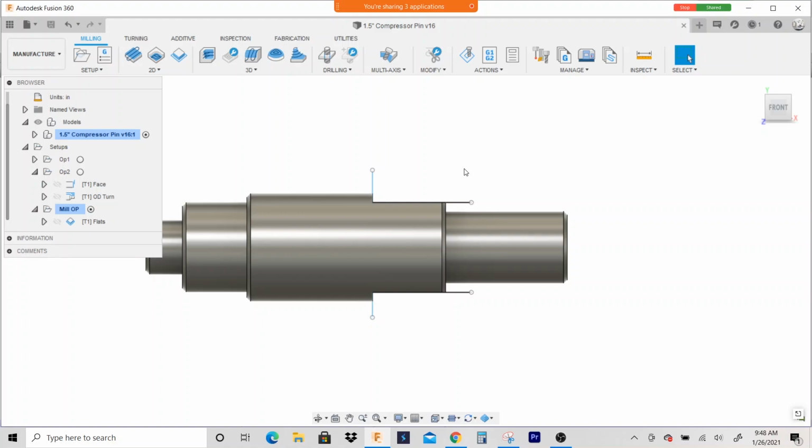So if you have a machine that's not rigid, like you've got little bitty motors on it and it's kind of underpowered, it adds more cutting force, so it could actually pull the part out.